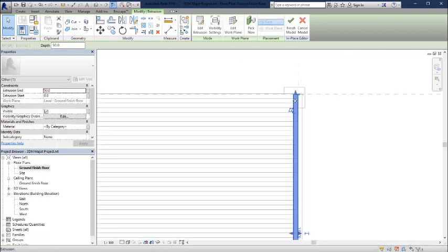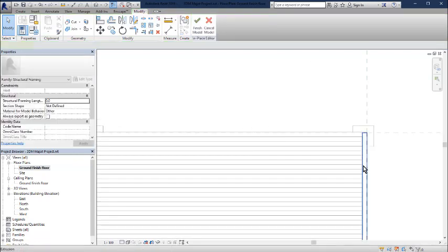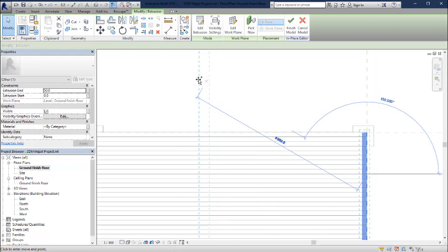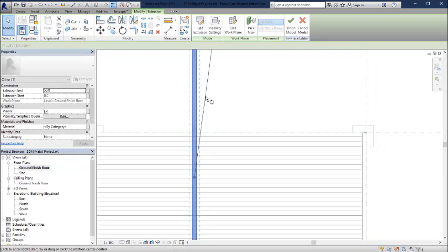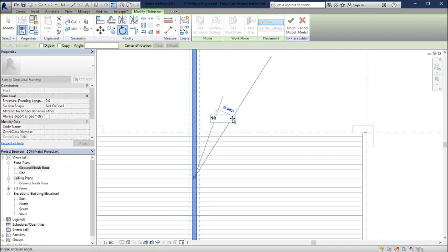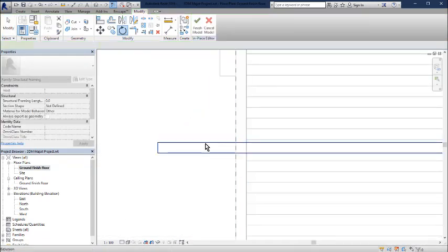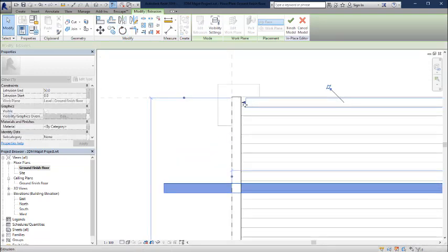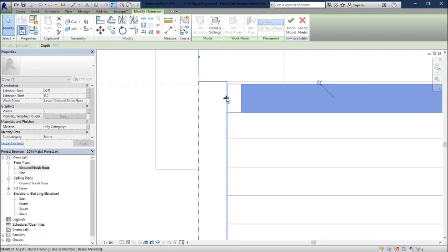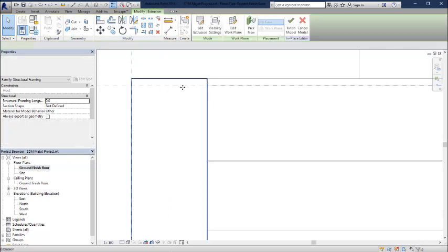Oh, that's where we were. Alright, and then we're gonna copy this again. So we're gonna click on it, CO, copy, and let us rotate that. RO is a shortcut to rotate, and 90 degrees. There we go. And we're gonna move this in place here, and we are gonna align here. Let's move this. Actually, that's where we should move it.